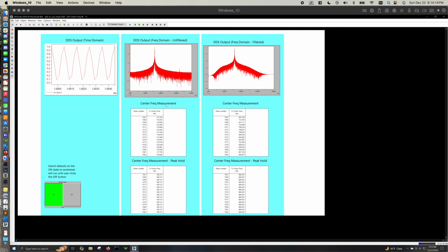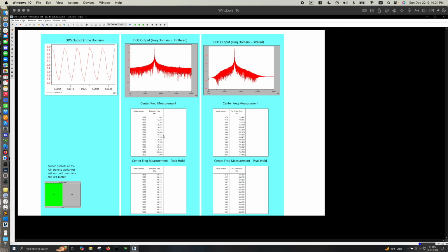As you can see, you can kind of see what I meant about how there is a little bit of jitter, so seeing exactly what the peak is equaling out to is kind of tough just on the straight amplitude measurement. So you can see where that peak measurement option is pretty necessary here.